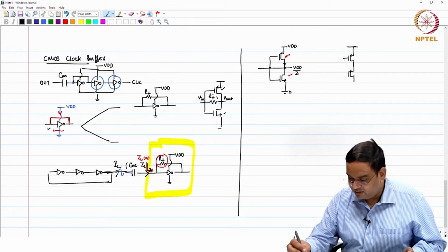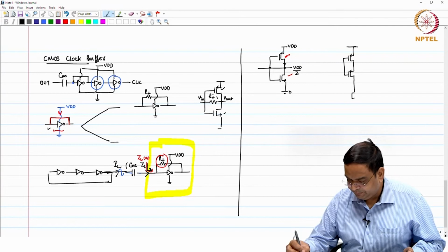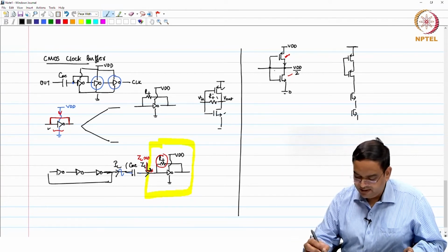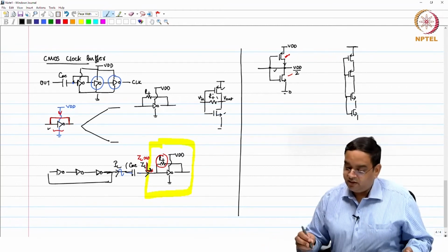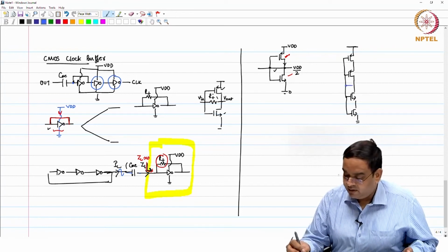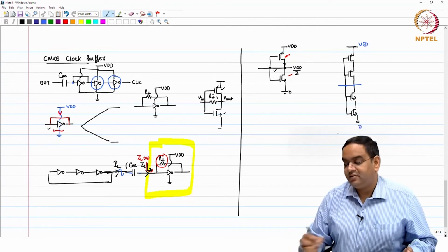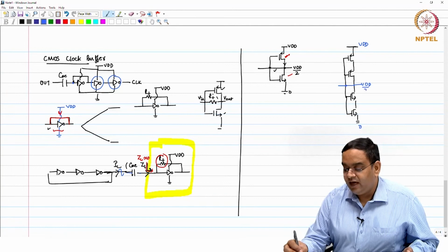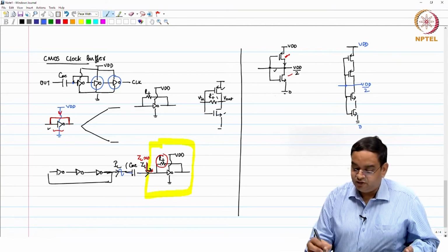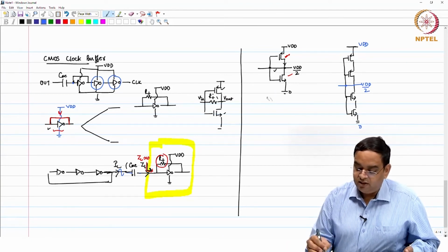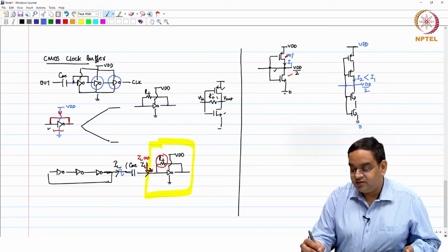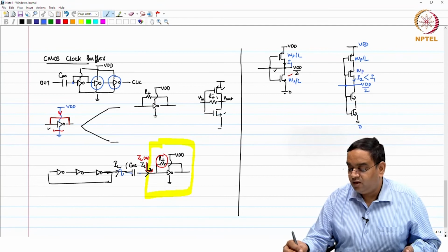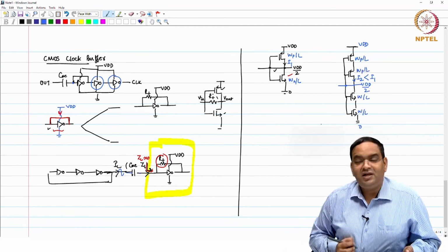So, what I do, increasing the length, is typically the same as this. So, in place of using the self bias inverter as shown on the left, I go and use the inverter as shown to you on the right. Okay. So, if I do this, then I can very well design this circuit in such a way that this voltage is also VDD by 2. The current consumption in this circuit, so if I call the current flowing here I1 and the current flowing here I2, your I2 is surely less than I1. I am using the same MOSFETs, let us say WP by L and WN by L. So, this is WP by L, size is the same. So, if I do this, then the I2 current is going to be lesser.